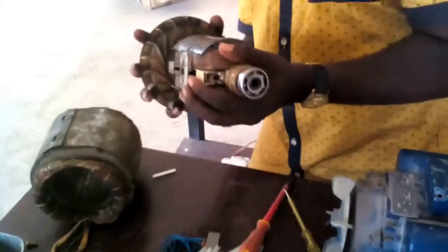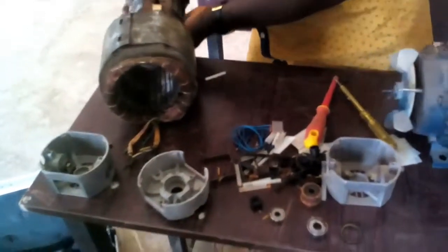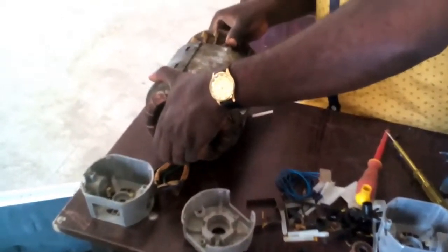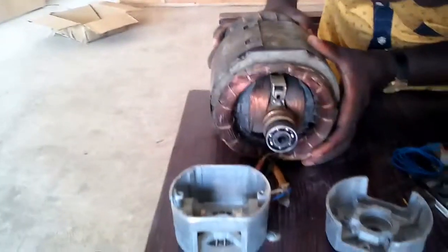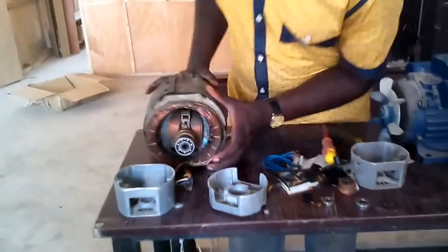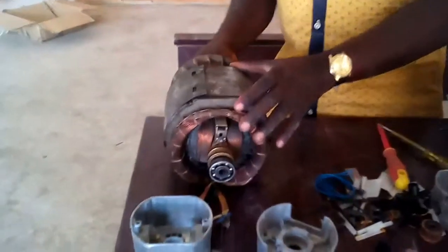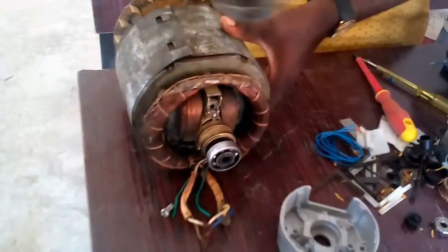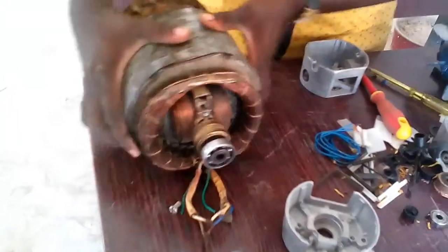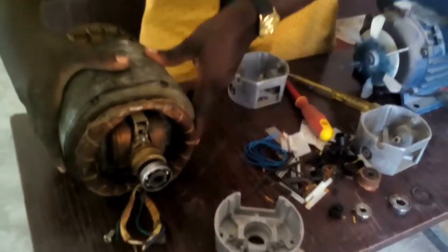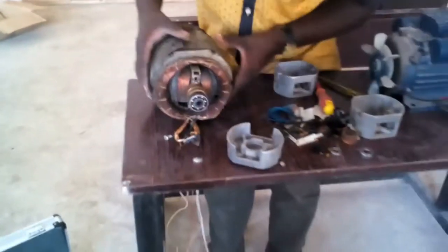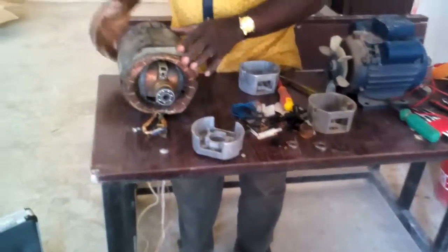We also look at the issue of the foundation. Supposing it is the foundation that is defective, as you can see inside the system winding there, the most likely possible cause is to check the base, the foundation on which the machine is resting. If it is not properly aligned, or if the foundation is not balanced, then definitely the machine will be vibrating. The remedy is to realign the foundation to make sure that the motor operates smoothly.